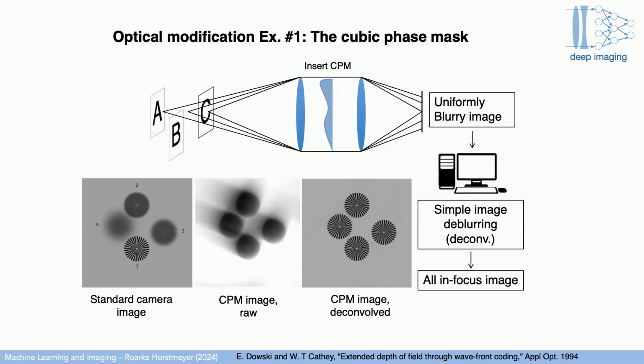So the people who invented this, they're pretty smart. They started a company and I think sold this to OmniVision for like $15 million. A while ago now. Because it's a simple way to extend the depth of field of a camera, right? But it only made it into a few systems. And the reason why is because of the challenge of performing an accurate deconvolution. Right? Even though this mask is designed to have a well-posed deconvolution process, it still didn't work too well. And so I don't think it's used that much, but it did make it into some commercial cell phones.